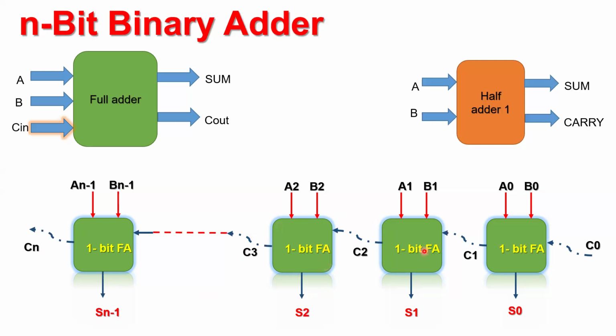You can see that this is also called a series adder circuit. Why? Because you are adding the initial 3 bits, assuming C0 is equal to 0, and you have two outputs available, S0 and C1. Then C1 propagates to the second stage, giving the sum and the carry output of this stage.